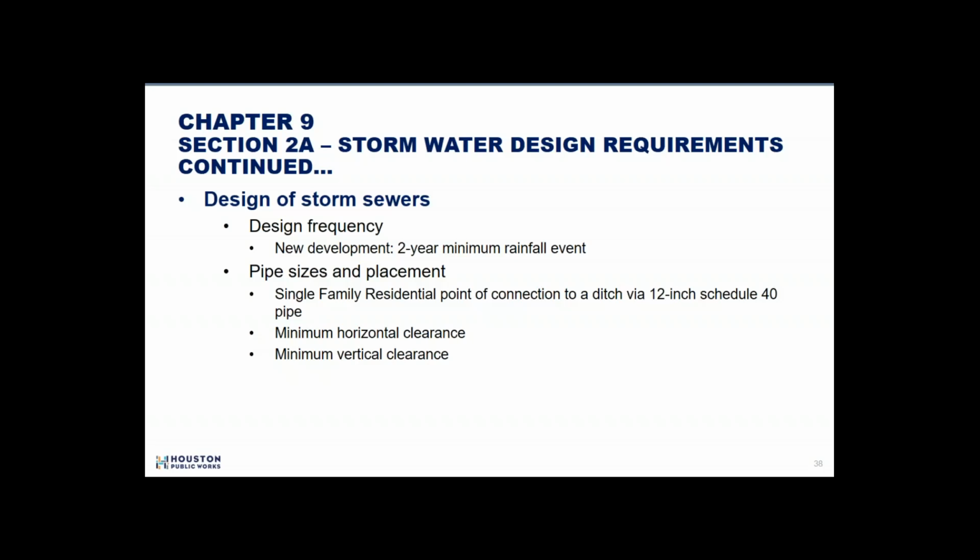So we are basically eliminating these two items, siphons and conflict manholes, so that the stormwater maintenance system can be properly maintained. Stormwater quality can properly be maintained, if you would. So be aware of that as you move forward on your designs, so that we don't have issues in the future.